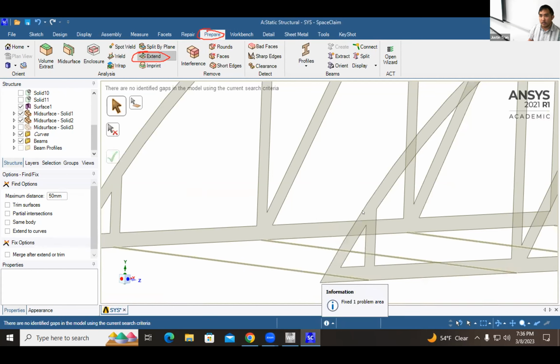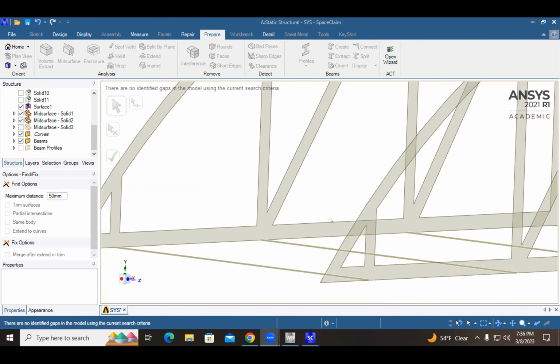Question: how did you get the numbers to show up for the move tool? I click move and I see the arrows, I just need the number to show up. You're going to click on the blue arrow and move it up with the mouse just a little bit, just to get the box to show up, and then you can enter the number right after that. Thank you.